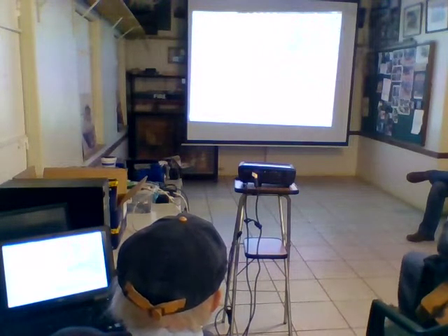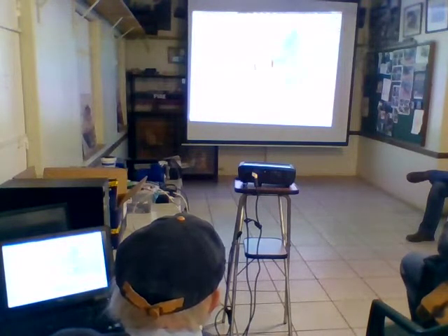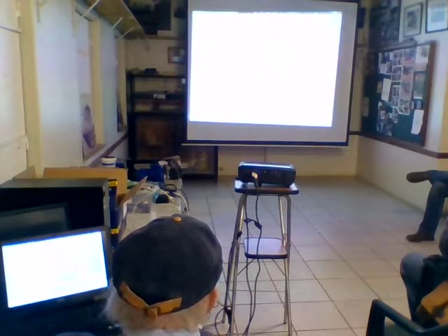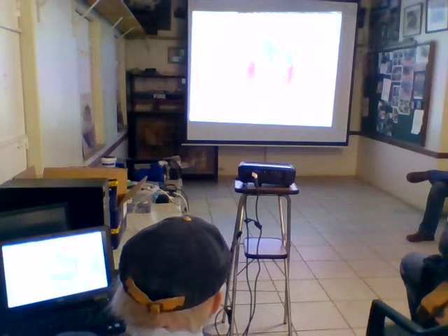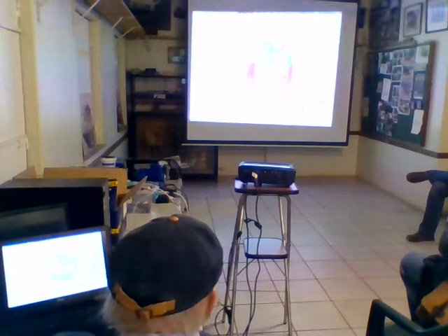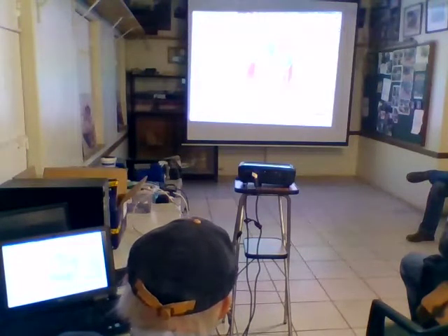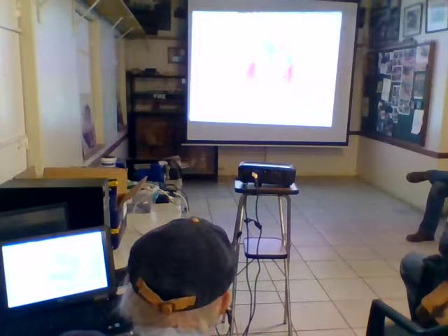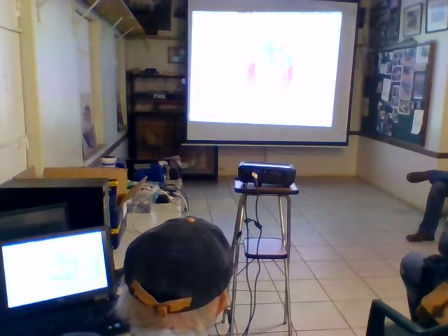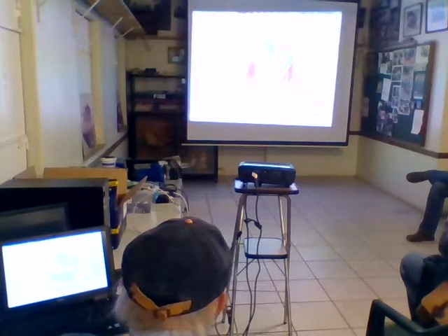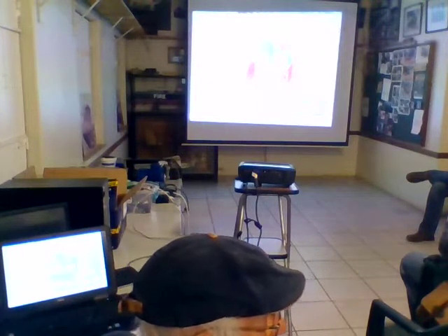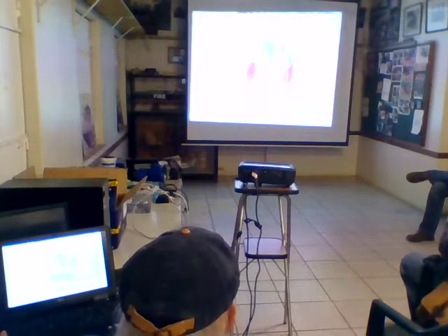The lead screws are just a single element, a very roughly made approach. But the main thing here is to get an idea of the performance of the machine, in terms of when you apply forces here on the tool, what happens to the machine. So I've got a couple of loading situations which I can run here on a time basis. First I put a force in this direction, in the lateral direction. I take it off and then I put a force in the forward rear direction, and then I put a force in the vertical direction. And if I run it here on a time scale, you won't see any movement because the movements are so small that you can't see it with the eye.